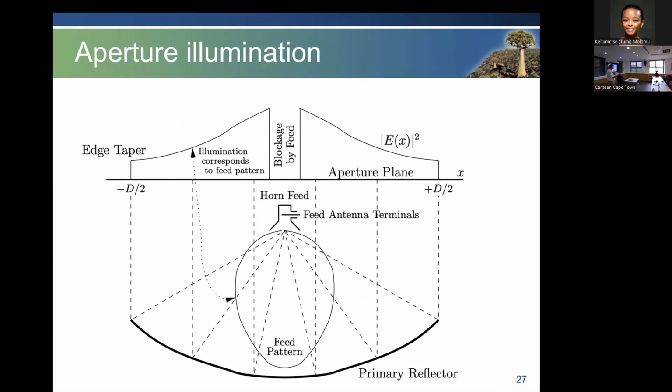So let's move on now. We're going to be dealing almost certainly only with reflector antennas. So this is a simple sort of one-dimensional view of a center-fed reflector. So we have a primary reflector, which normally would be a parabola. These days we shape these things so they're not just pure conic surfaces, but if you have a parabola, it's got a focus, and you go and stick your feed at that focus.